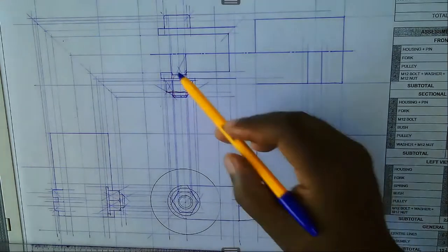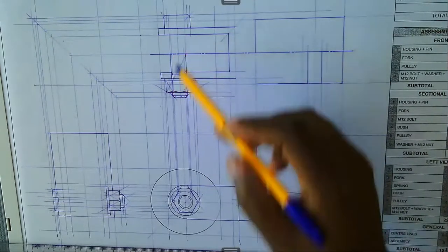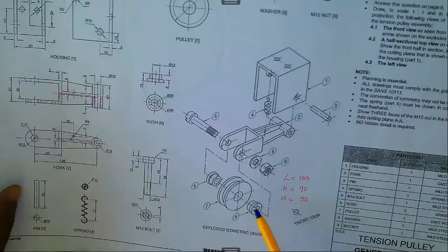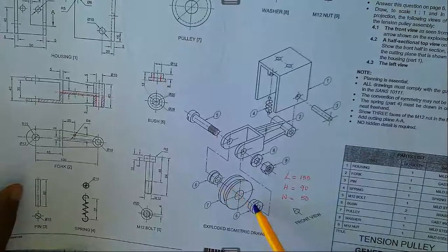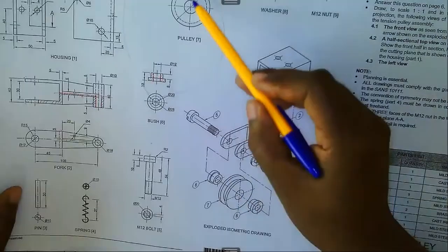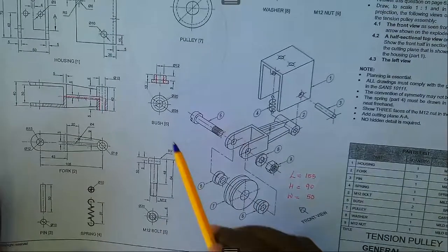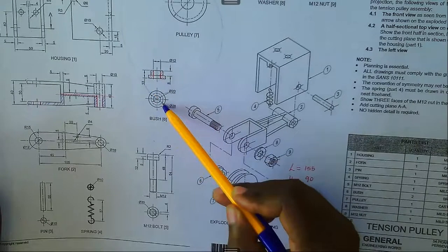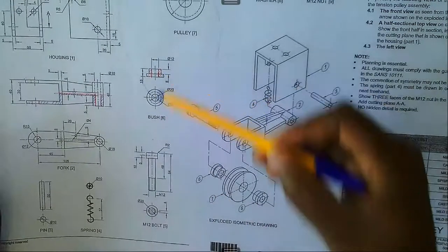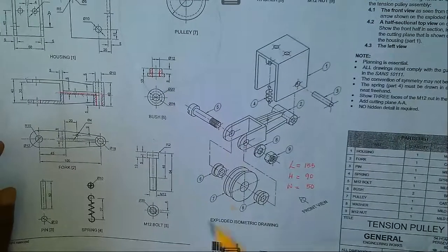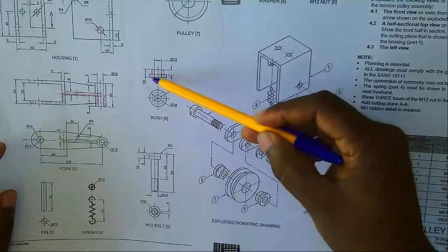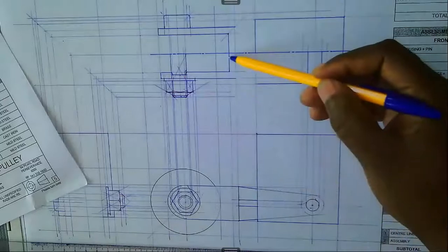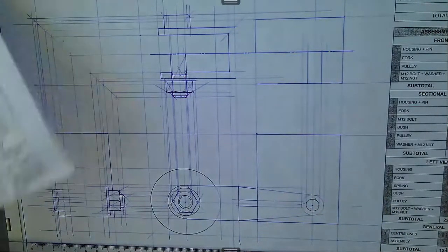Right. Before we define the pulley, there is also the bush in position. Right. The bush will get into the pulley. We have got the pulley, the inside diameter is diameter 20. But if we look at the outside diameter of the bush, with regards to this part from here to there, it's diameter 28. So it's only this part that will get into the pulley. So the rest, from here to there, we are told that's 18, and from here to there, that's 8. So 5 millimeters and 5 millimeters, that's our bush.